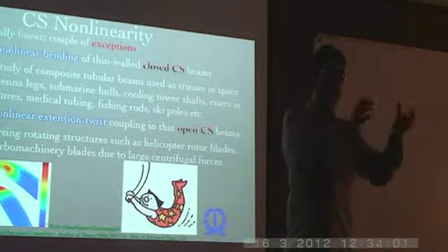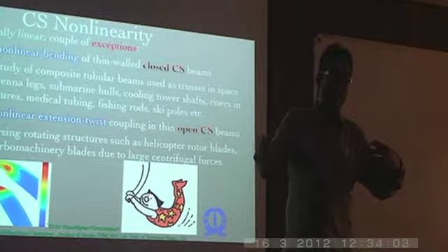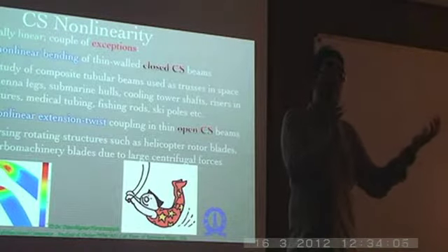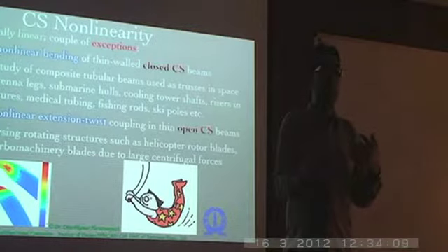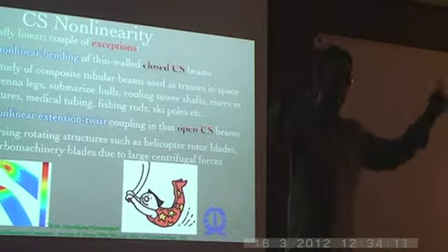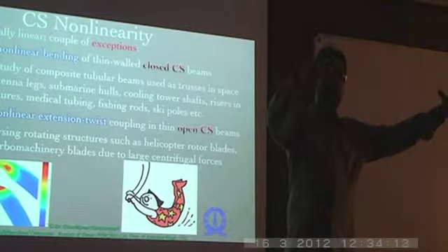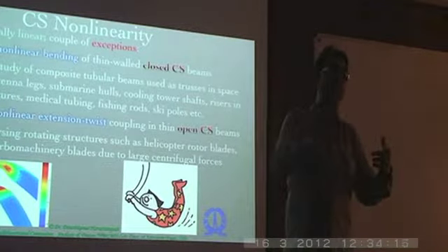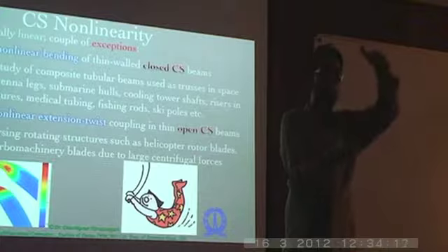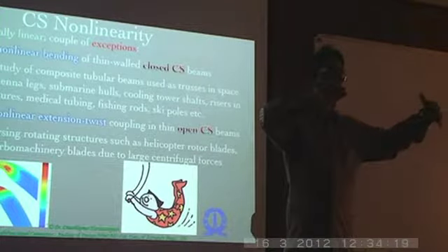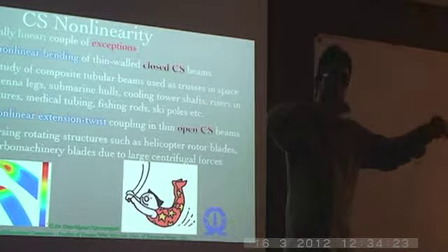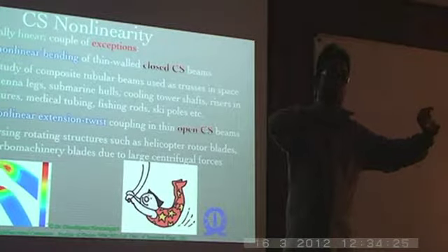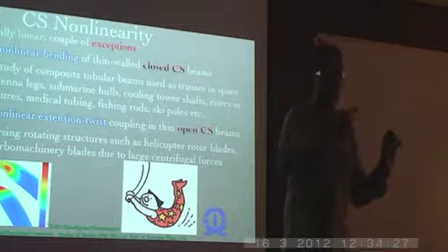When you're looking at it component-wise like that, then you would see how the load gets distributed. So you know that most of the bending goes into the stringers and the spar flanges. The torsion basically goes into the webs and the skin. So now you're basically seeing that the primary effect of this particular torsion is basically in a closed cross section.